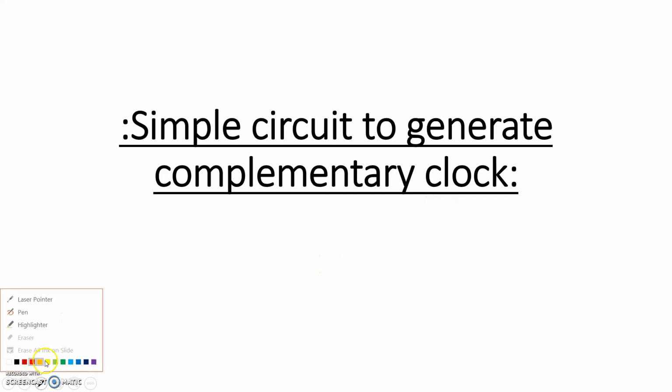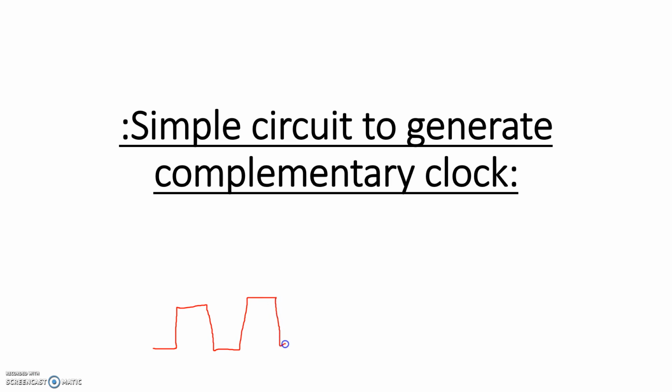A clock signal is basically one kind of square wave which is used to synchronize a synchronous circuit in digital electronics. It has its own rise time and fall time, and it oscillates between VDD and 0 volt, right? Although I have not drawn it properly, it is one kind of clock signal, which is very important in digital electronics or VLSI circuit design courses, obviously for synchronization purposes and to operate your sequential logic circuits and so on.